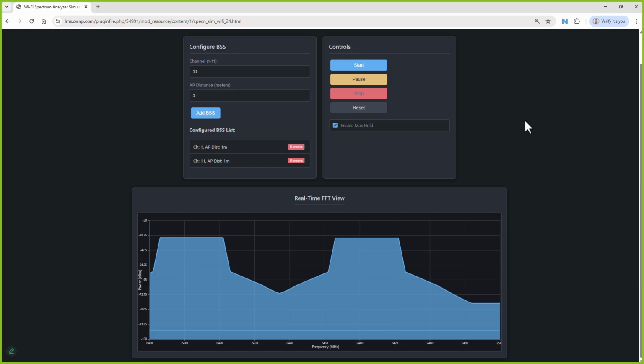The reality is that sometimes what you do is you have software configurable radios. And so you may be able to have one that is either 2.4 or 5, and then another one that is only a 5 gigahertz radio, right? That's something that's been implemented before. So if you decide to put both of them on 5 gigahertz, what you don't want to do is have them on two different channels that are right side by side in the 5 gigahertz band. So you may want to use one of the lower channels and one of the upper channels, right? Give significant separation between them, because those two radios, their antennas are now right there in that box together.